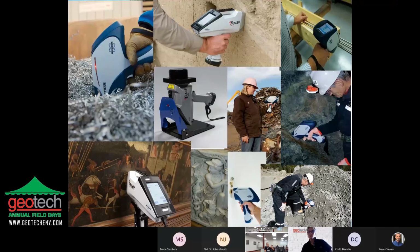So I just want to point out with these applications, you always want to put the instrument directly on the sample. Air causes error. You want to be as flush to the sample as possible so that all those X-rays that you're exciting and coming back to the detector can read those characteristic X-rays. You want to make sure they come back to the instrument.